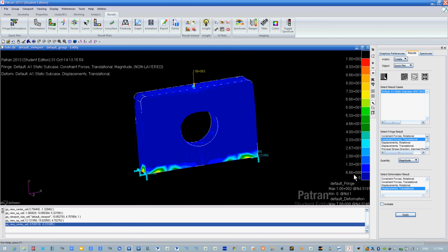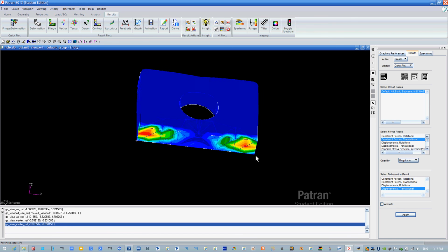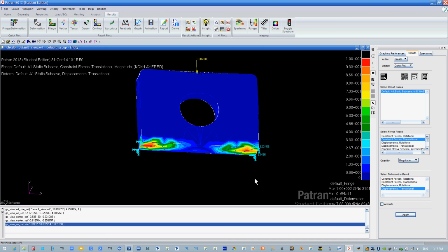So on the right, we can get an idea of the magnitude in some of the regions. Oh, and this brings up another good point. When you increase the mesh count, theoretically, if you've set up your model correctly, you should converge to finite values. If you have your model set up improperly, with bad geometry, when you keep increasing the mesh count, the value balloons to infinity. So that's also important to take into consideration.